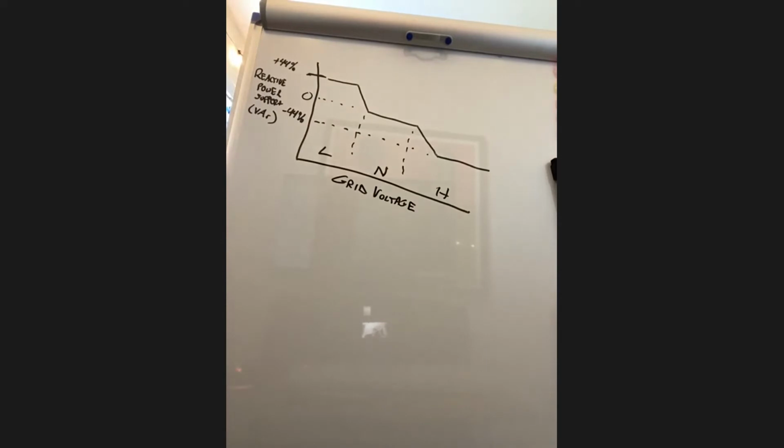And so the industry saw that things like volt-var curves or even fixed power factor settings, which are related to a volt-var curve, are an extremely important feature that DERs need to have in order to support a healthy grid ecosystem.